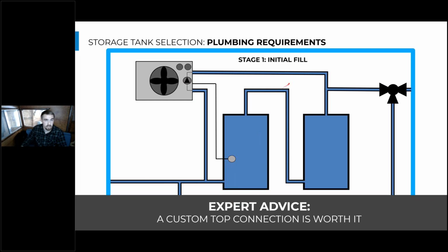Right, and another thing to point out here is, for simplicity and animation, we have this heat pump outlet tied in next to the mixing valve, which goes against what I just told you about separating those connections. So take this connection with a grain of salt, but it still illustrates the stratification in these tanks really well.